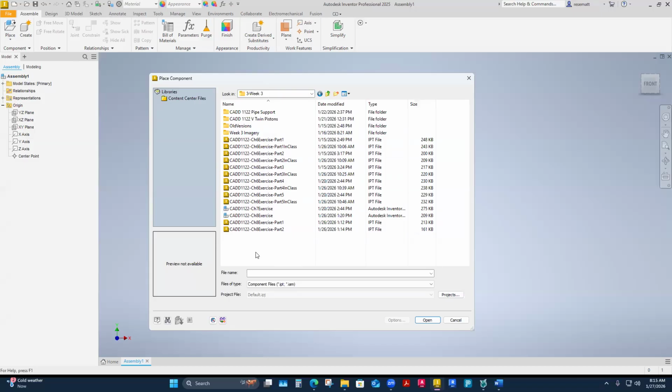Generally, when I build an assembly, when I'm working on a job, I may have a folder with the job number on it. I think I mentioned this. Within that job folder, I might have a few subfolders, which might be parts, assemblies, and drawings. Sometimes I put my parts and assemblies in their own folder, and that helps me not have such a huge folder to manage. I can easily find my parts and my assembly. My drawing might be in that initial first folder because it's the master.